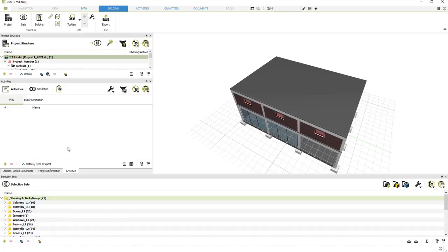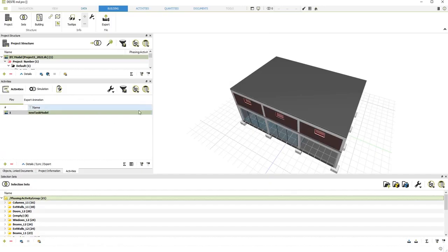So now we'll try to create the schedule for all the tasks we have for the activity groups here. The layout of the schedule is mentioned in page 12. So first I'll start by selecting the green plus here and select Create Time Schedule. Then I'll start adding the tasks one by one, but then I need to add the start and finish dates and the connection to the activities, so predecessors.